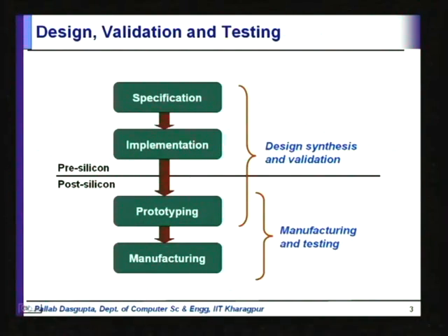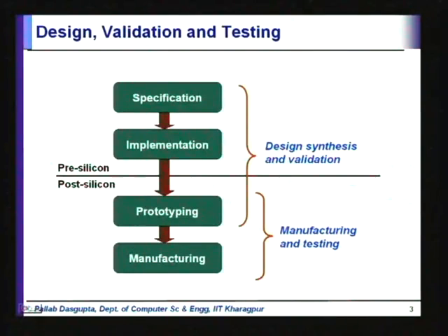On the other hand, when you have a first silicon available to you, then you can actually run that with an actual clock, and it is going to run much faster than you would be able to check it in the pre-silicon, right. So, that is why a lot of prototyping and hardware emulation is done, and that is also part of the design validation, because it may still point out errors in the design itself, the logic of the design itself.